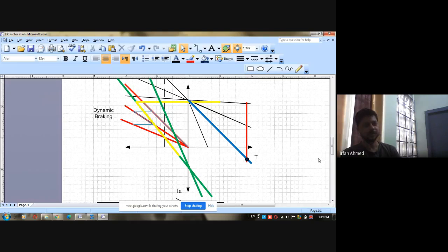So your hoist is moving at a certain speed. On the 4th floor, you add more material. Again, you move the hoist up. So now your speed will decrease. Correct? At the 5th floor, you add even more material. Now you try to move the hoist up, but the hoist will not move up. Its speed will remain 0, even though you are applying motor torque, because the load torque is so high. Now at that point itself, if you add even more material on the hoist, your hoist will start coming downwards. Okay?